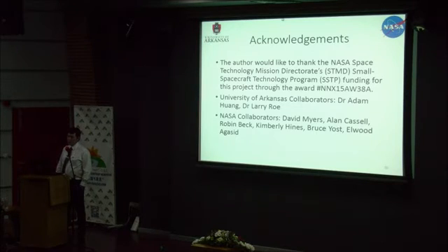To my knowledge, no, not unless they're heated very near their decomposition temperature. What is that temperature? 325 C. So if you get that hot by accident, your CubeSat's gone. It's dead anyways. Yeah, but just from the sun, it may heat up to 100 degrees. So I did one test. I left a beaker of it on a hot plate at about 150 C for a month, and couldn't detect a change in mass. Don't do this; it's bad for your hot plate. That was my quantitative test.